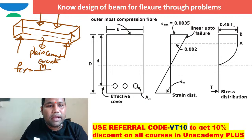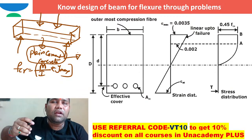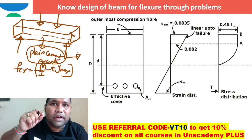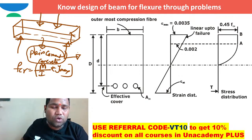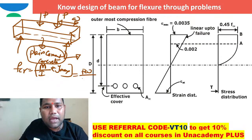moment of resistance, M by I into Y max. Based on this formula, because it is plain cement concrete, it is a single material. It is not a composite material. When it is a single material, I am free to use the flexure formula directly to evaluate bending stress and also bending strength. So to evaluate that bending strength, FCR is equal to M by I into Y max. If this is P, and this is A, M is equal to P into A.